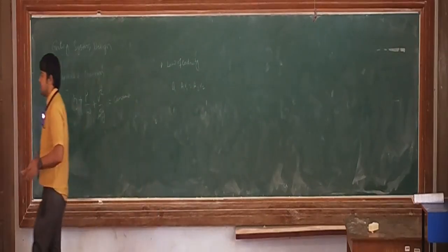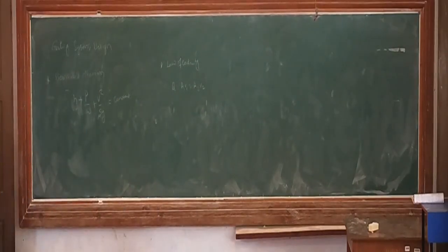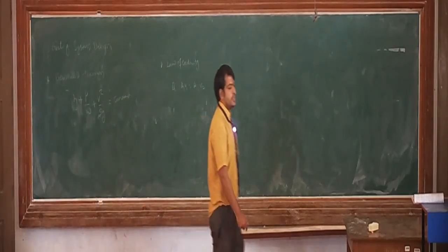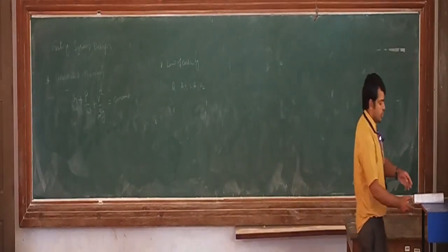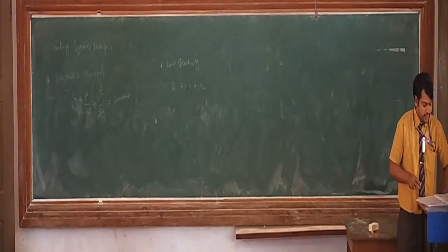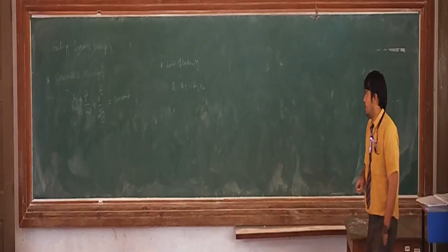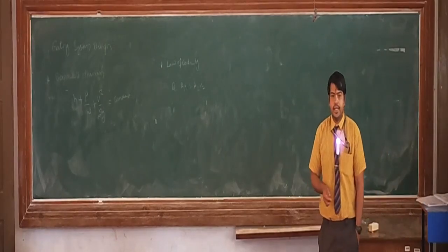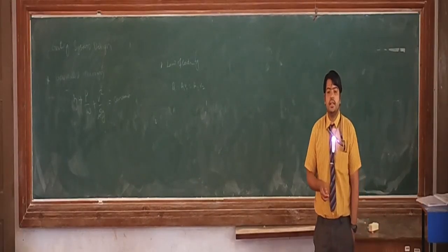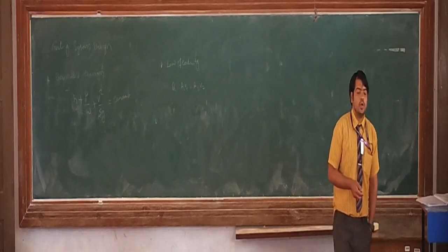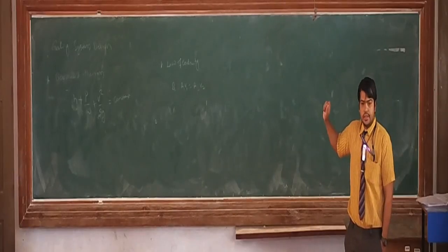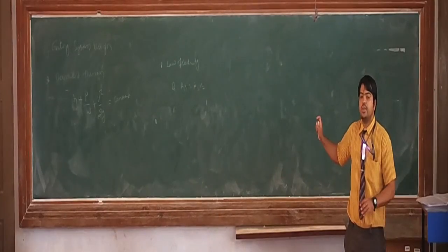But coming to this point, the gating system design is done by using two basic principles of fluid mechanics. One is Bernoulli's theorem and another one is the law of continuity. Bernoulli's theorem states that the energy head is going to remain constant at any section in the mold cavity, with respect to the mold I am talking about. So it is going to remain constant.